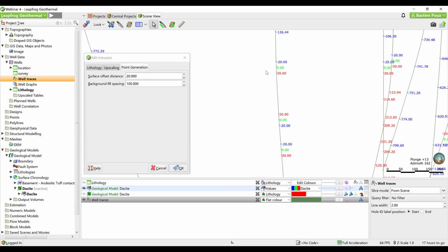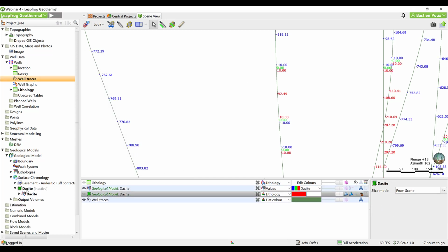The surface offset distance parameter sets the top and bottom ends of the interval and affects how a surface behaves when it approaches a contact point. A smaller distance restricts the angle that an approaching surface can take. We are going to lower this number to 10, and you can see that the interval for the surface to pass is much smaller.